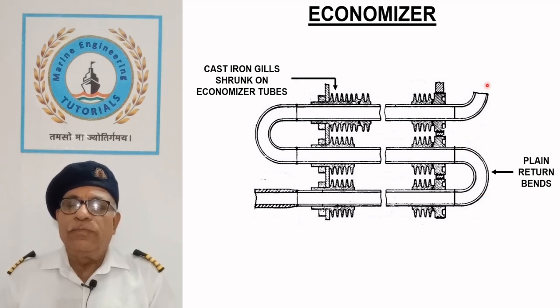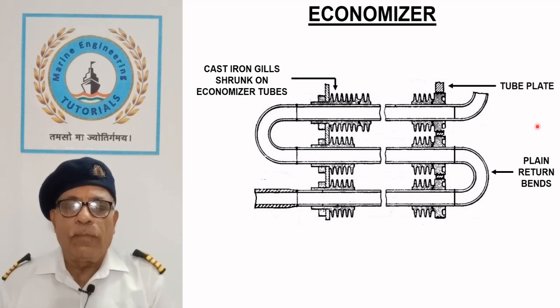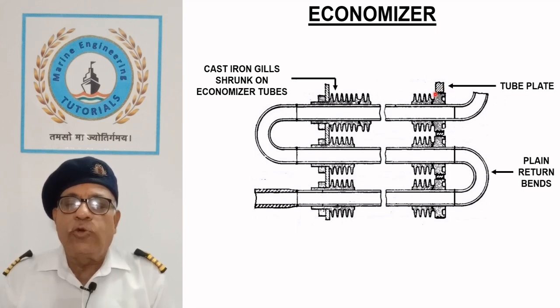The return bands are plain without the gills, and are used to connect the gill tubes. Return bands do not form part of the heat transfer member, as the exhaust gases do not flow around them. Gill tubes are supported by tube plates on either side and also provide free expansion and contraction. Tube plates also form the passage for exhaust gases.